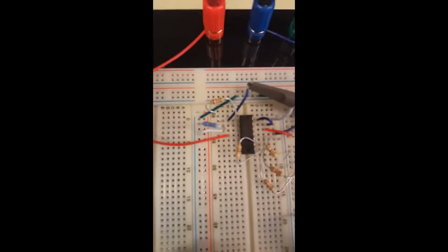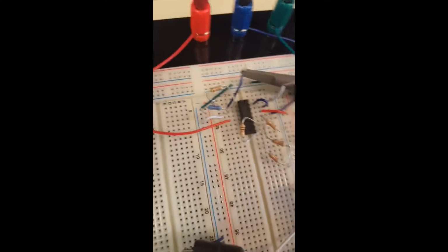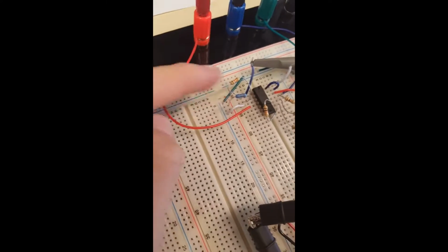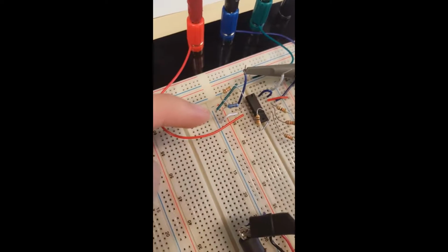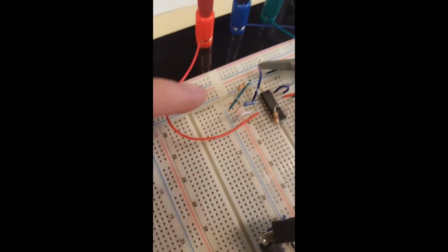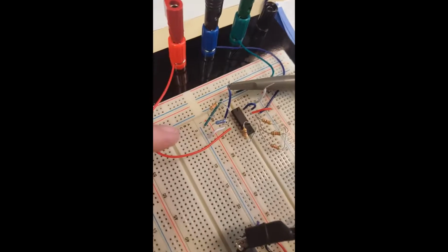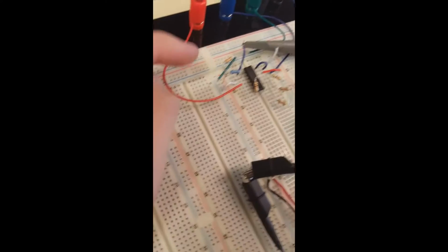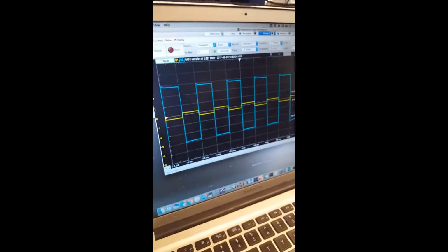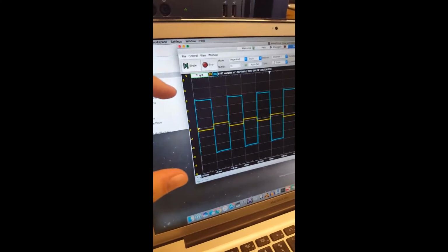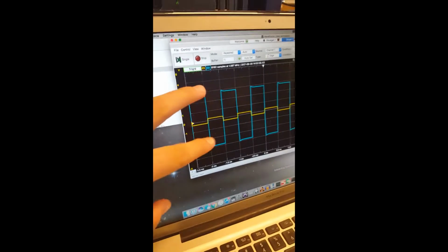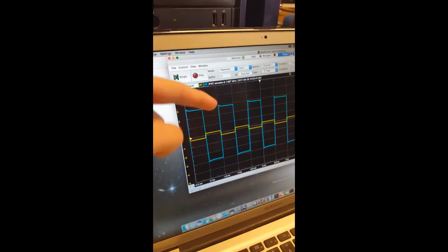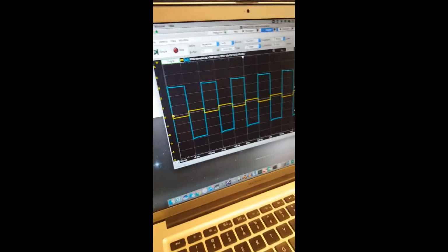Okay, so here in the upper left corner is our inverting circuit, and we have chosen the resistor values to be such that the gain is 12. So we have a 12 kilo ohm resistor and a 1 kilo ohm resistor hooked up as in this diagram here. That results in an output that looks like this. So the output is significantly higher than the input, and it's inverted, so the valleys correspond to the peaks, and the peaks correspond to the valleys.